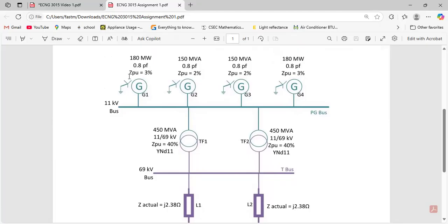For the generator, they will give you the per unit impedances as percentages. We just convert it to decimal form. And those per unit impedances are represented at the particular MVA base of the generator right now. So first off, this will have to change to MVA. I'll go through a video where I do the calculations, but for now, just to understand. These two have to change to MVA, and when they change, you'll notice that all four generators will be at a different MVA base.